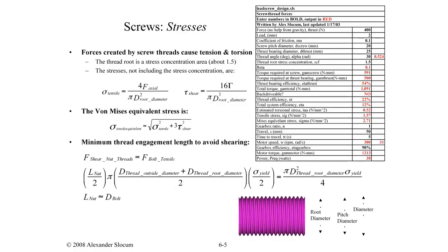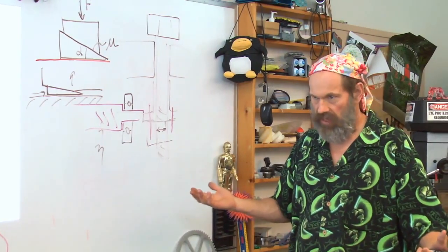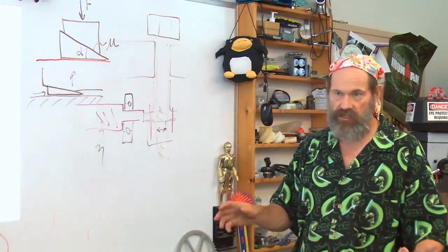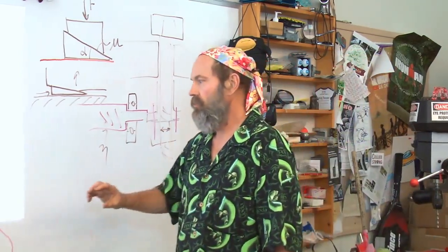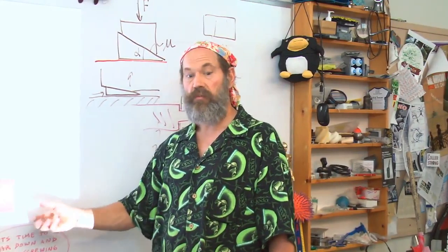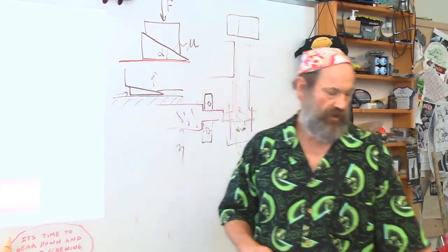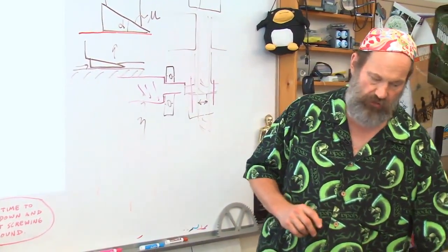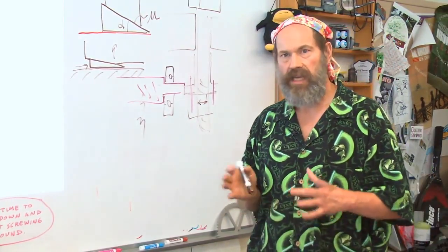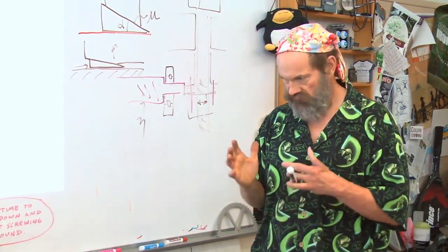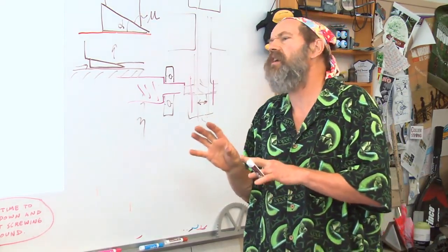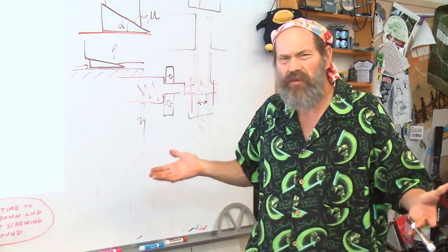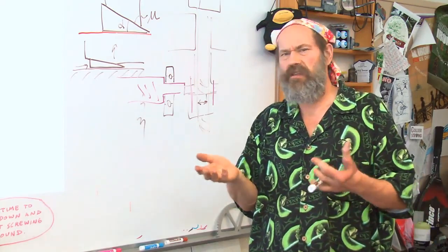Now, you figured out, I apply the torque to the screw, I get this much force out, the losses, the efficiency, fantastic, great, go for it. You also have to be worried that you can put so much torque on the screw that it breaks. There is a rule in designing heavy equipment that you never ever use, depending upon the company, anything less than, for example, an 8mm diameter bolt, even to hold on a little cover plate. Why do you need such a big bolt to hold on a little cover plate? This is ridiculous. Get rid of those bolts.